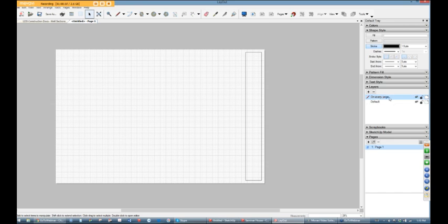You can leave it like that. I usually change that to title block. So I would double click and change that maybe to title block. And everything that's put on that layer will show up on every page. It's what's called a shared layer. This last box back here on this line is the option to change things to a shared layer.